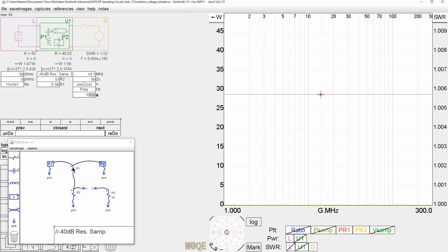But the power, unfortunately, on R1 is 28.8 watts. Trying to put 28.8 watts in a small package is not going to work. First of all, any kind of resistors that you put here would have to be resistors that were heat sunk. Heat sunk resistors have 3 or 4 picofarads of capacitance on them.